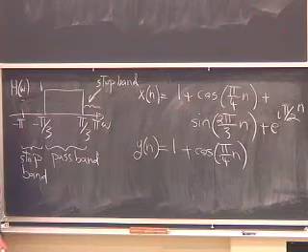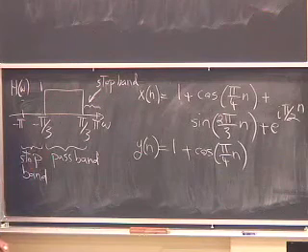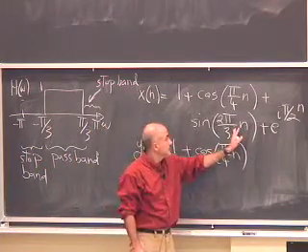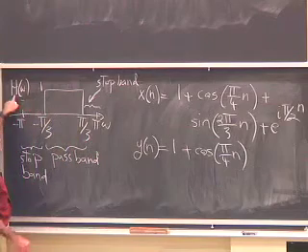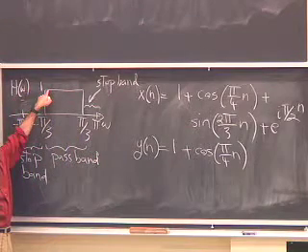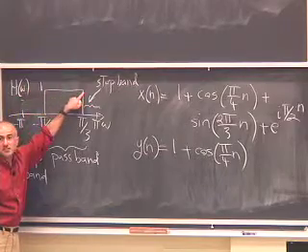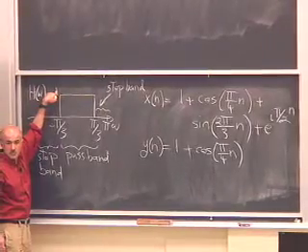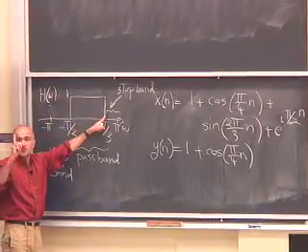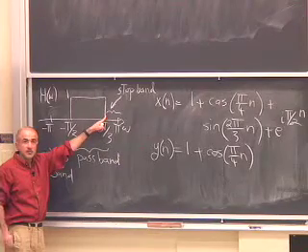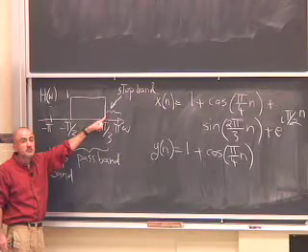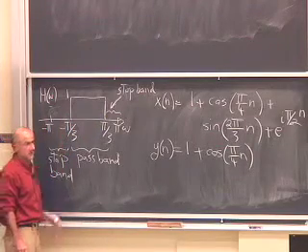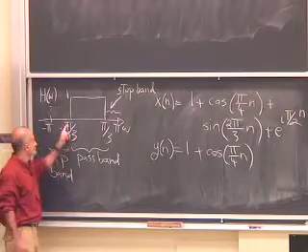You don't have to break the cosine into complex exponentials. You don't have to break the sine into complex exponentials. Because this filter is real valued. Whatever it passes, it passes with amplification 1 and phase of 0. Its magnitude in the passband is 1, the real number 1. And the phase of the real number 1 is 0. And whatever it kills, you don't care about the phase. 0 has undefined phase, but it kills it.